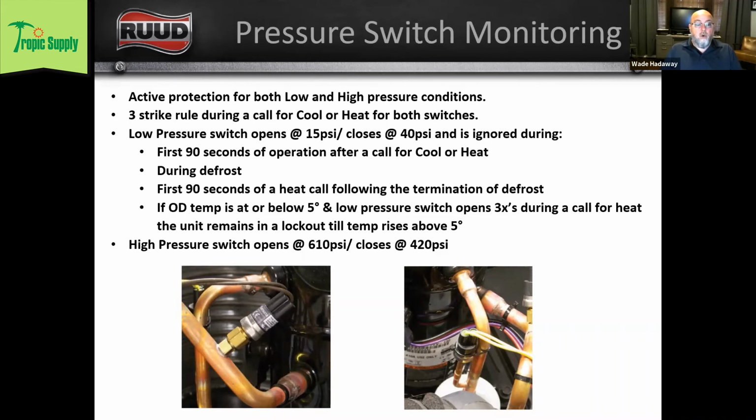monitor, or it ignores that low pressure for the first 90 seconds of operation, whether it's a call for heating or cooling. It ignores low pressure during defrost. It ignores low pressure for the first 90 seconds of a heat call after defrost.